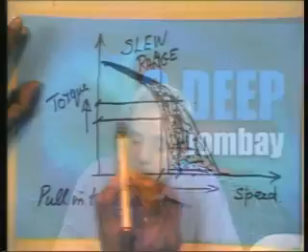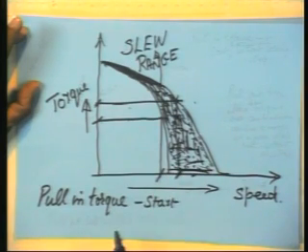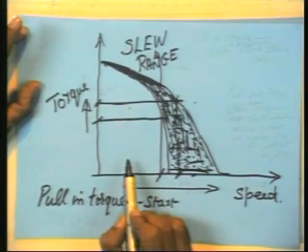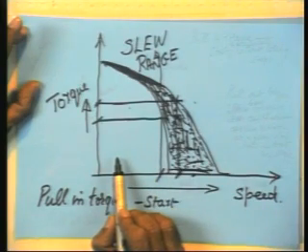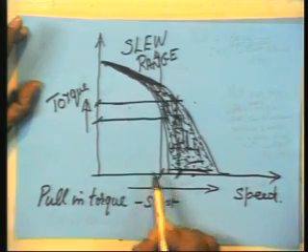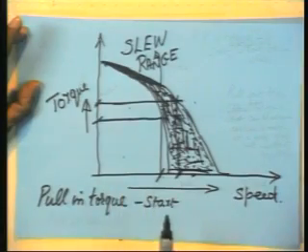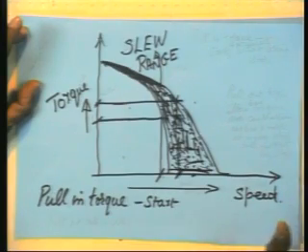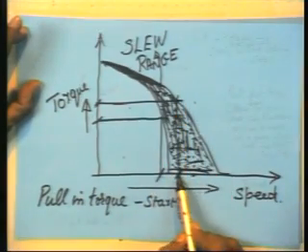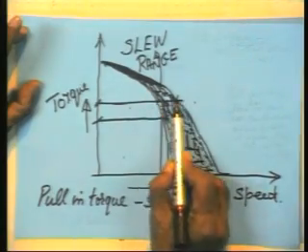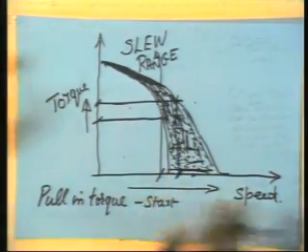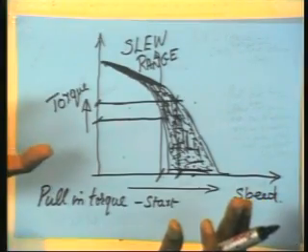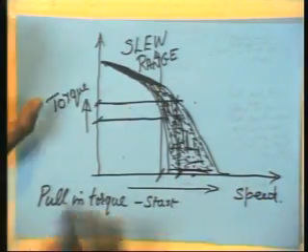Another thing, let us look at it again. Given a torque load, there is a maximum speed beyond which you cannot comfortably accelerate or decelerate. This is the speed. Given a torque, if you are moving at a constant speed in this zone, it will be synchronized with the switching, it will follow the switching without losing steps. Beyond a particular speed, it will start losing steps.